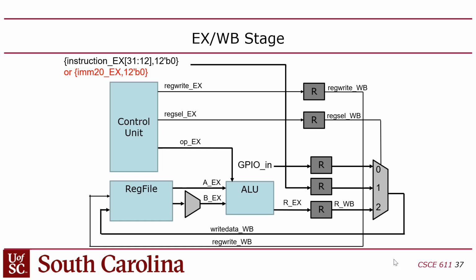And then we have reg-select, which is probably the most complicated part of the data path control, because this mux is controlling, well, it's not really clear what it's controlling because this port isn't labeled. But the output of this goes back to the reg file. The intention here is to decide what value to write, not where to write, because where to write it comes straight from the instruction, the RD field, right?